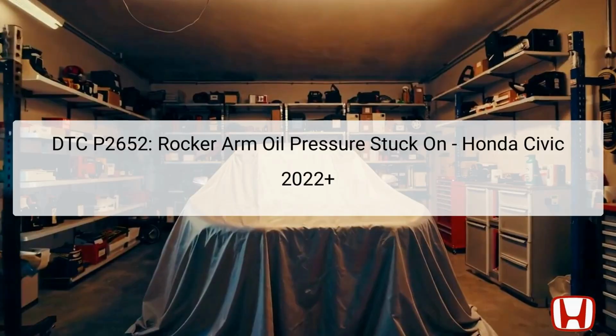This presentation aims to address the diagnostic trouble code DTC P2652, which indicates a malfunction related to the rocker arm oil pressure being stuck on in the 2022 and newer Honda Civic models. The DTC is triggered when the output from the rocker arm oil pressure sensor remains excessively high while the rocker arm oil control solenoid is turned off.